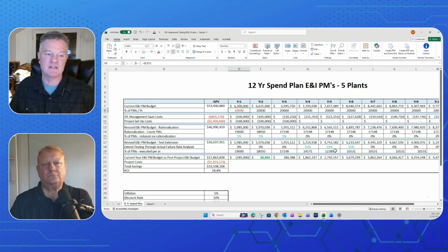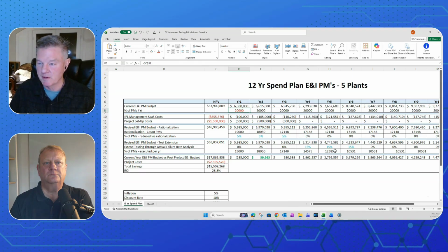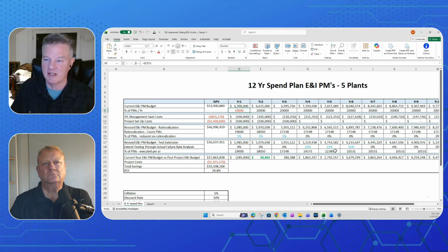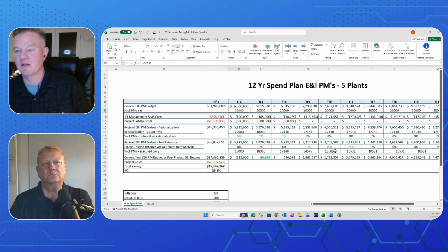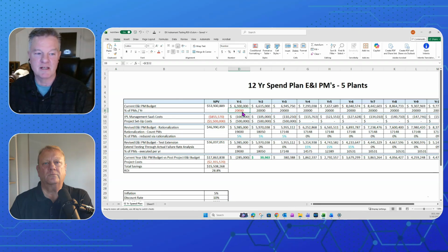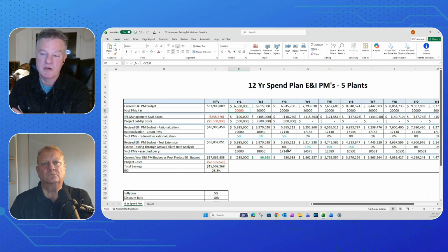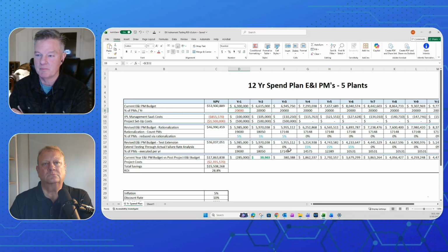While we don't need SIL calcs for all this stuff, and this is a little commercial thing as well, it's really fast to set up a template for an alarm with operator action for a pressure transmitter. You engineer that one time, and then you just populate that. You load SmartPlant data or AVEVA data and instantiate, and it's done in seconds. And no one has to think. And guess what? There's a reliability model in that. So every one of these things gets built out with a mini little reliability model. If we have 20,000 pressure transmitters in there, I change the failure rate in one place, all 20,000 calcs updated.